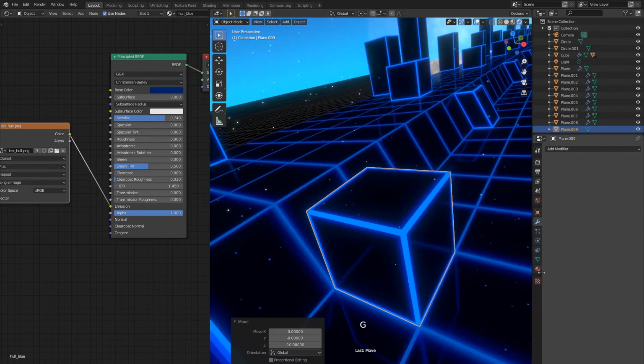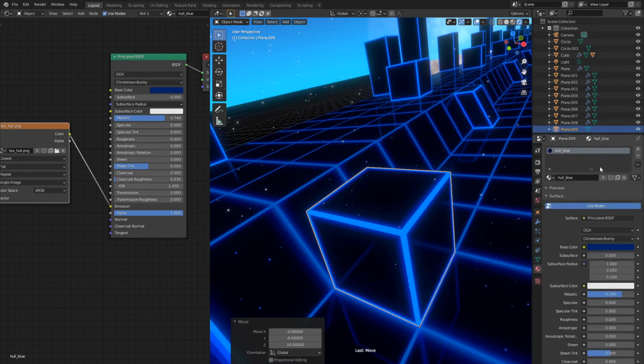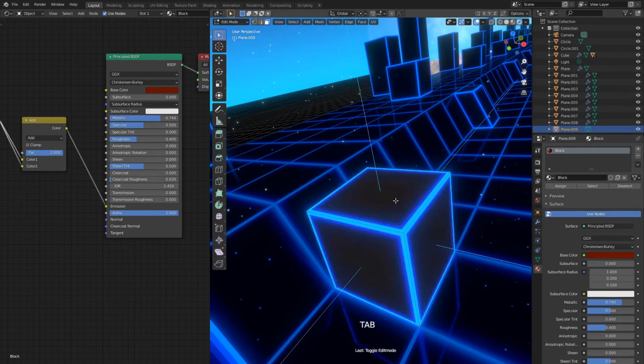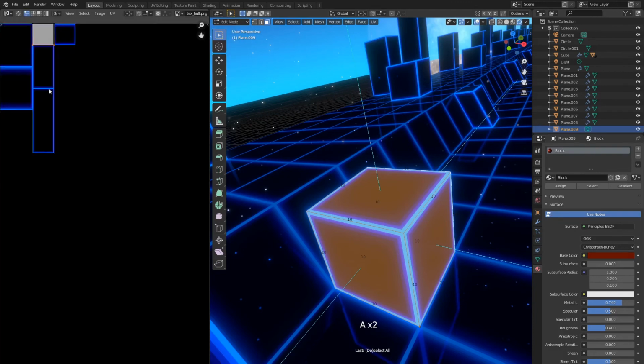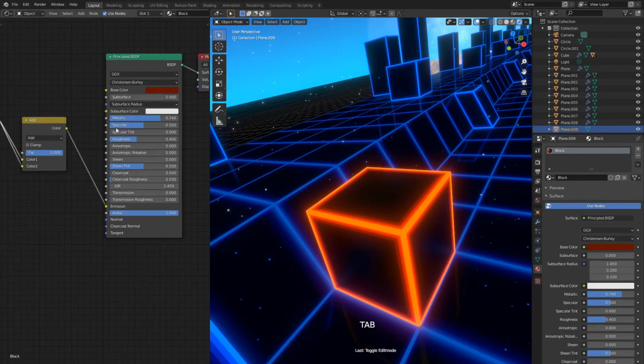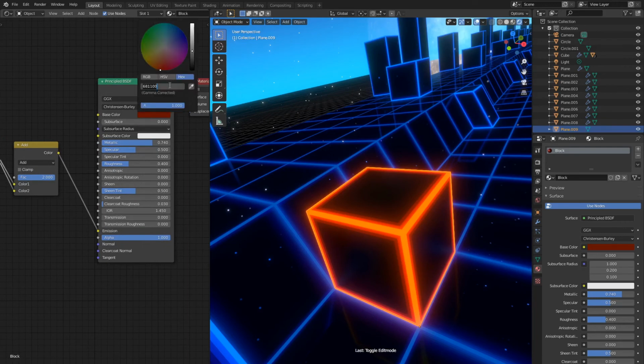Now let's create a material for our obstacles. We want them to be red, so let's duplicate hull shader we've previously created for the spaceship. Rename it to block. Now we need to remap all faces to a red square on the hull texture. Go to the shader editor. And let's make its base color a bit darker. OK, and now set specular and roughness to be 0.